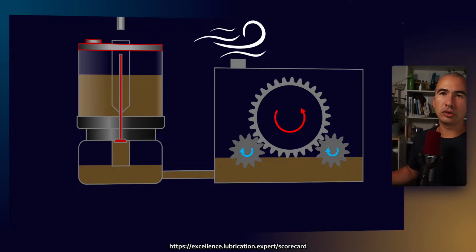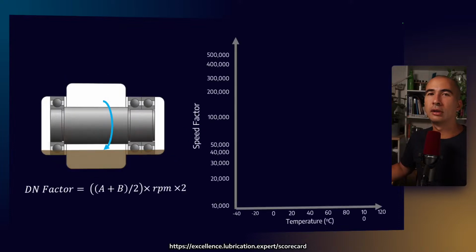The other thing that we want to do is we want to be cognizant of the Venturi effect. So as I'm showing this air blowing over the top of the gearbox, right? If we have a breather up there, that can cause the oil level to rise on the inside. So sometimes they actually connect it back to the constant level oiler. All right, so that's constant level oilers.